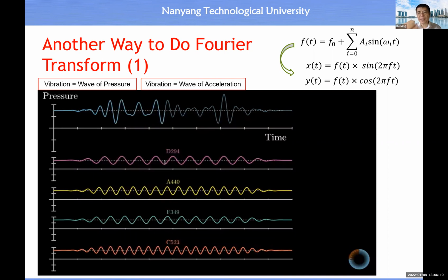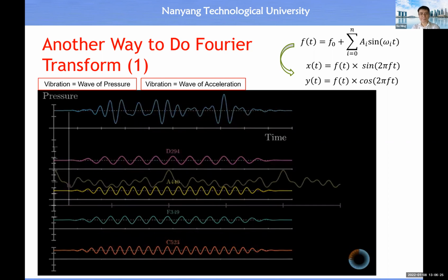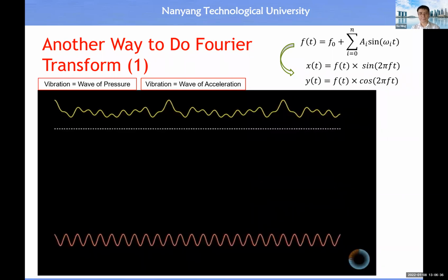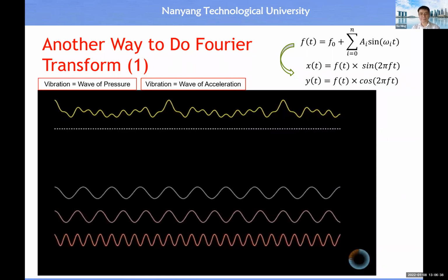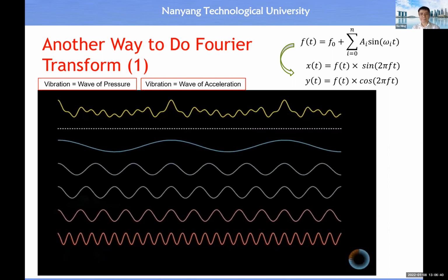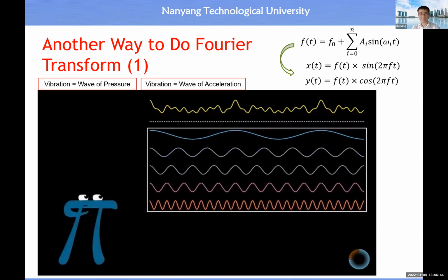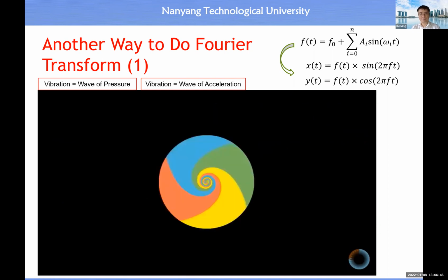So on top is f(t), complicated, right? Given the low amount of information put into it. A microphone recording any sound just picks up on the air pressure at many different points in time. It only sees the final sum. So our central question is going to be how you can take a signal like this and decompose it into the pure frequencies that make it up. Pretty interesting, right? Adding up those signals really mixes them all together. So pulling them back apart feels akin to unmixing multiple paint colors that have all been stirred up together.